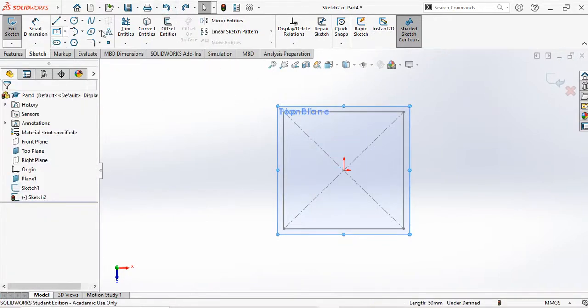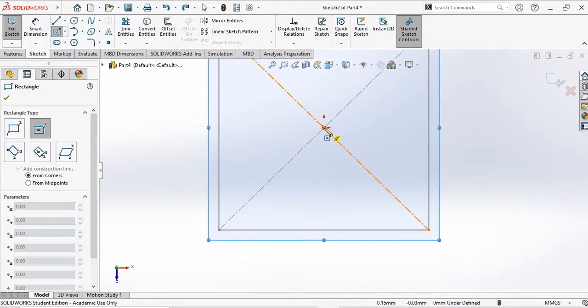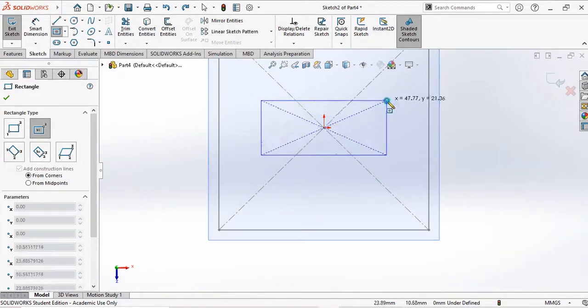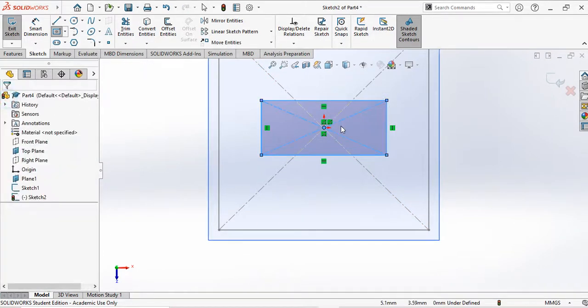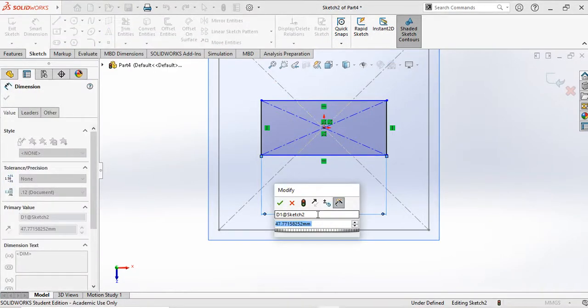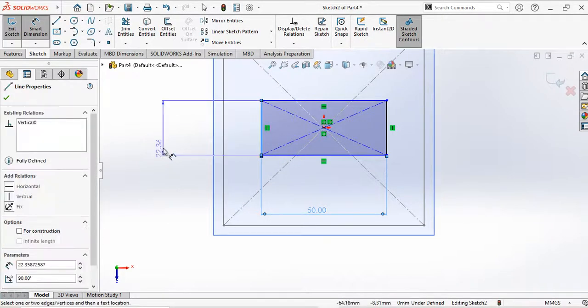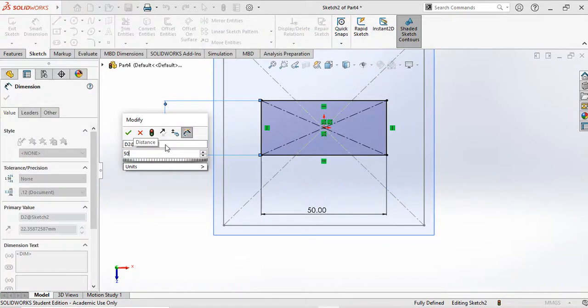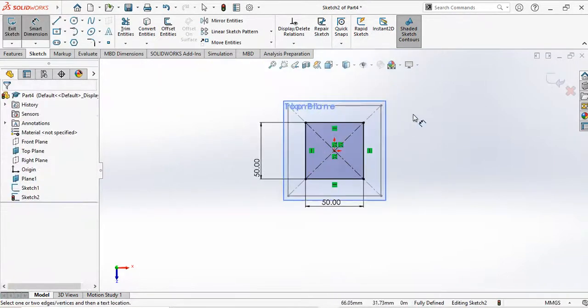So by right, I should start a center rectangle and make sure it's constrained at the midpoint. You will see a coincidence constraint. Just now when I added it, it did not form a coincidence, so it won't constrain at the middle. So this is 50, and it looks like this.